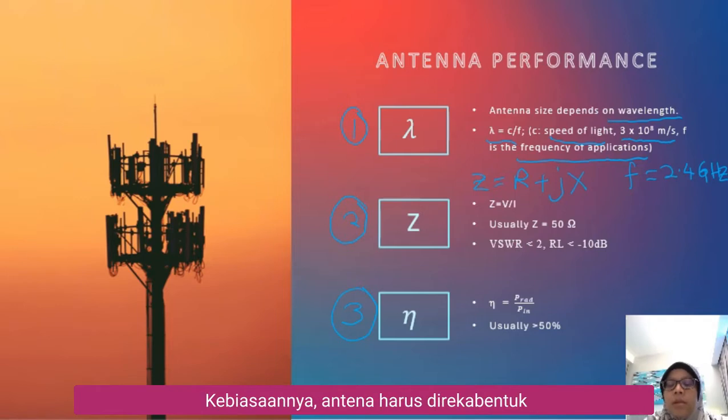In many cases, the antenna needs to be designed so that its impedance is equal to 50 ohm, in order to ensure that it is matched with other cables. So for a good antenna, the VSWR should be lower than 2 and the return loss should be less than minus 10 dB, where dB represents decibels. I'm going to show you later how a good antenna will produce this result.